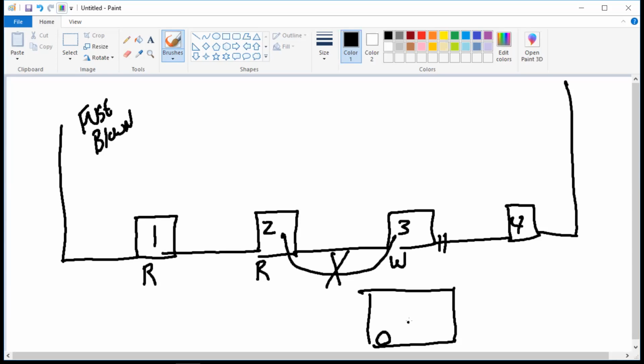You just drive by them and see whatever's flashing, and you go between a flashing one and a non-flash. Where's the fault at? Between 2 and 3. Flashing, non-flashing. This one will be flashing also. All right, sound good? One method of determining faulted span.